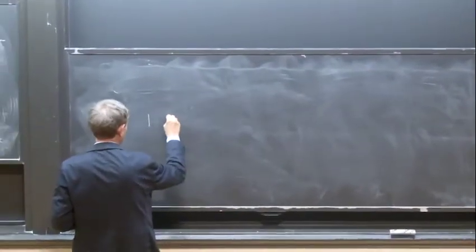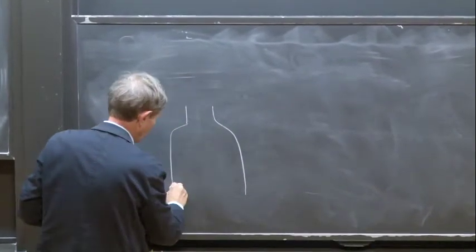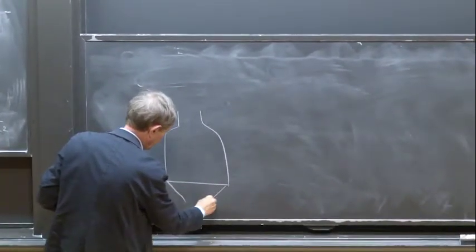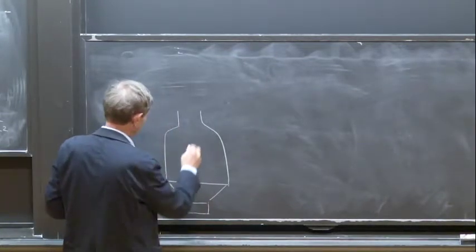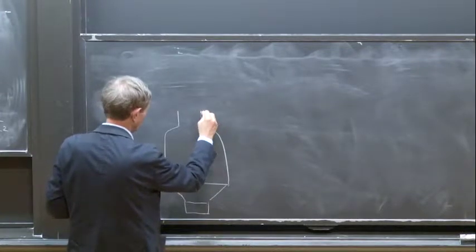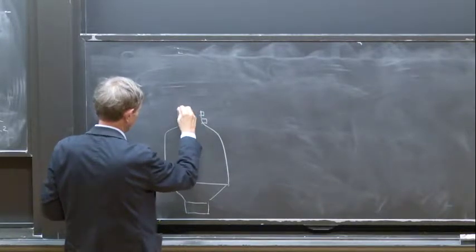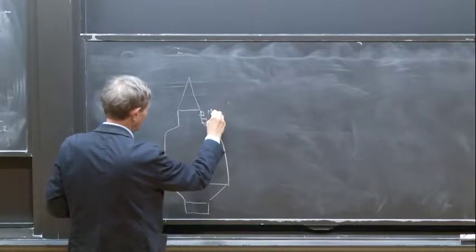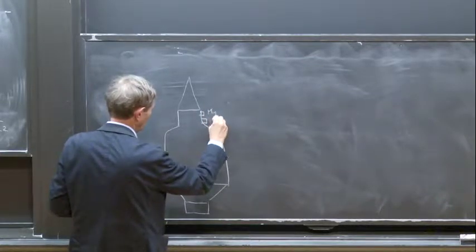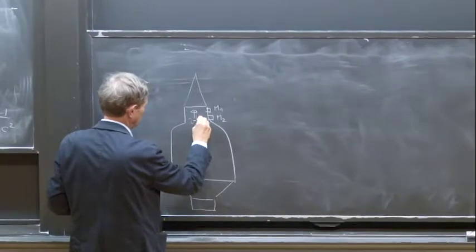So you have here your combustor, and you put the loudspeaker here. So this is a simple setup. And now what you can do is put two microphones here, just upstream of the flame. And let's assume that you have a conical flame here. You take these two microphones, M1, M2, and you produce the velocity fluctuation V prime here.